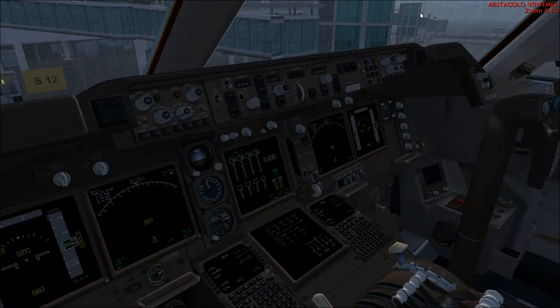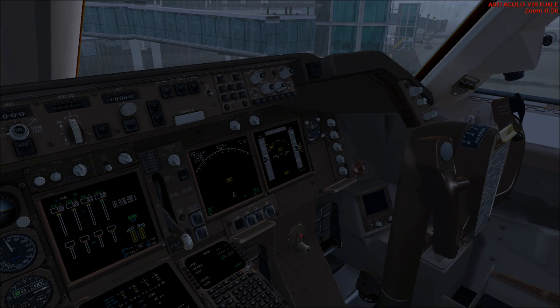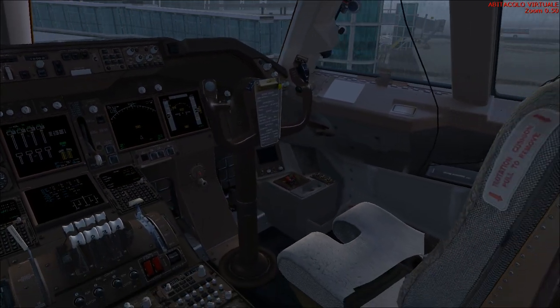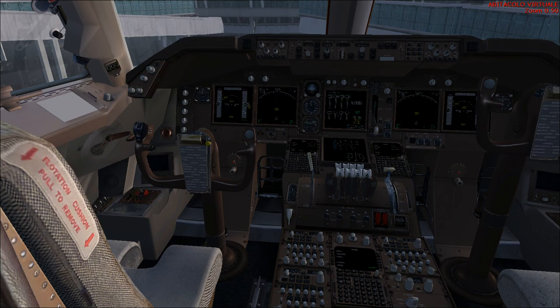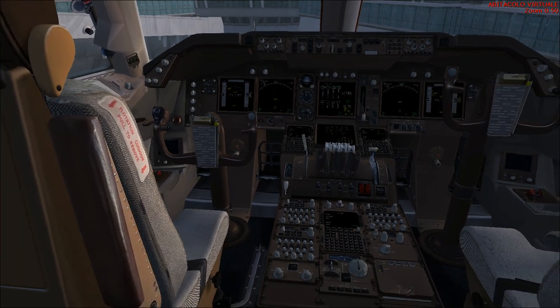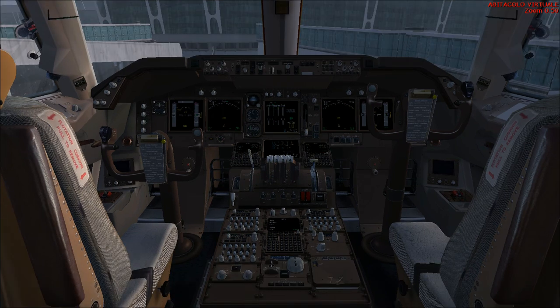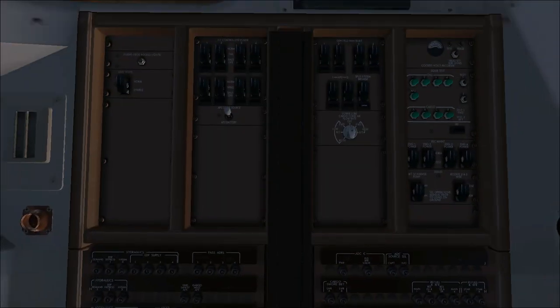At this point we have to continue and go to the overhead maintenance panel. Now we are in the maintenance panel, and we have to check some things. This procedure is done after a crew change or on the first flight of the day. You have to check that all the guards are closed, as you can see: ground test, flight control, hydraulic power, generator field, mine reset, split system breaker, APU maintenance and the fuel. All of them are closed.